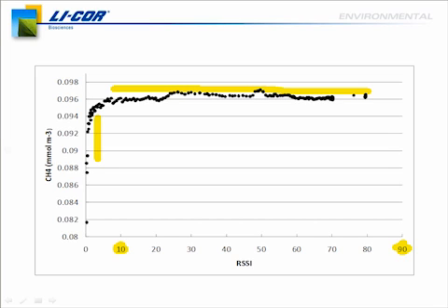Okay, thanks, Ashley. That's a good question. We'll go ahead and clarify that a little bit more. Corolla, the first part of your question was how often do you need to clean the optics, and it really is going to depend on the location where the instrument is operating. There's going to be some ecosystems that just have more dust and pollen and deposition hitting that mirror than others. We've operated these instruments in a lot of different places around the world, from northern Alaska in the Arctic, to the Everglades in Florida, and even to pollinating corn in the Midwest in the United States here. So it's really going to depend.